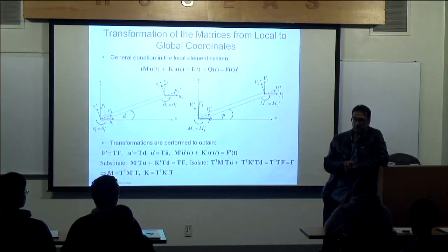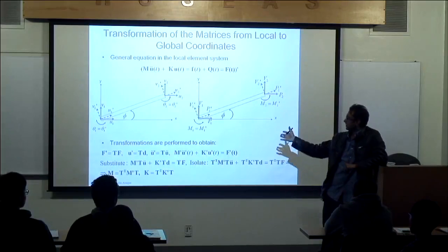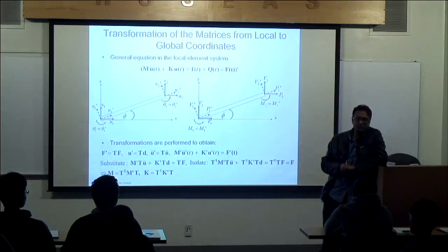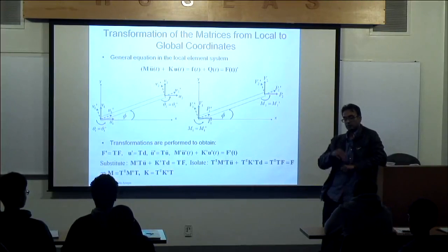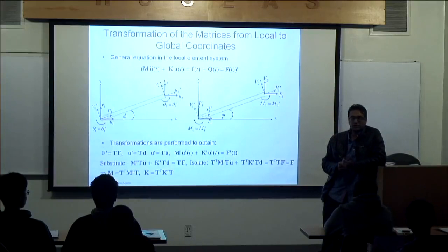Modal dynamics. What modal dynamics is, you can imagine if I have a 1,000,000 degrees of freedom problem, like an airplane or a launch vehicle, or a very large problem like an automotive part. There's millions of degrees of freedom, and I'm integrating all those equations of motion over time, and they're coupled. You can imagine the difficulty in solving that in an efficient manner. If the problem is linear in nature, then using modal dynamics is very, very useful.